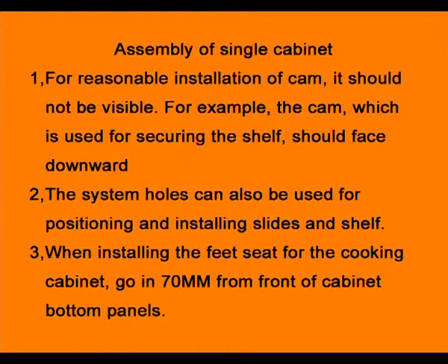1. For reasonable installation, the cam should not be visible. For example, the cam used for securing the shelf should face downwards. 2. The system holes can also be used for positioning and installing slides and shelves. 3. When installing the feet for the cooking cabinet, go in 70 mm from the front of the cabinet bottom panels.